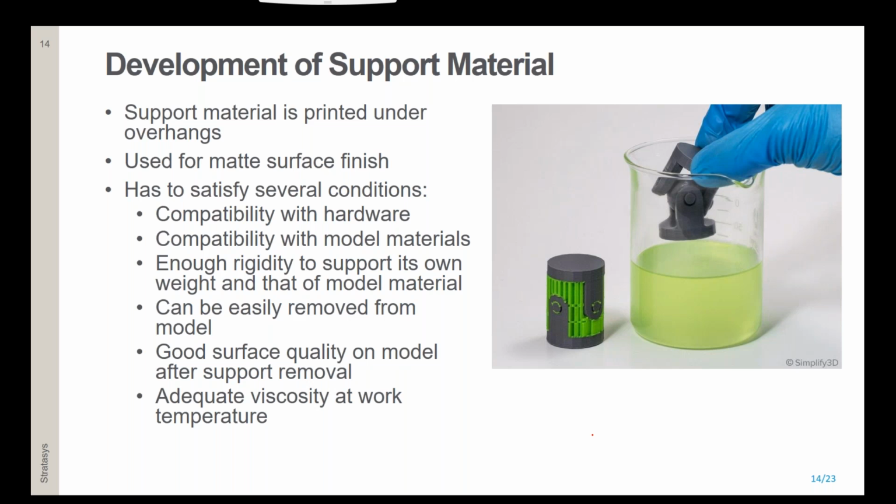So we are very limited with the types of materials that we can use for formulation. And this is a real challenge because, of course, you could increase the temperature of the print heads to match the required viscosity, but you can go only so high. You cannot get higher than, I don't know, maybe 80 degrees centigrade.